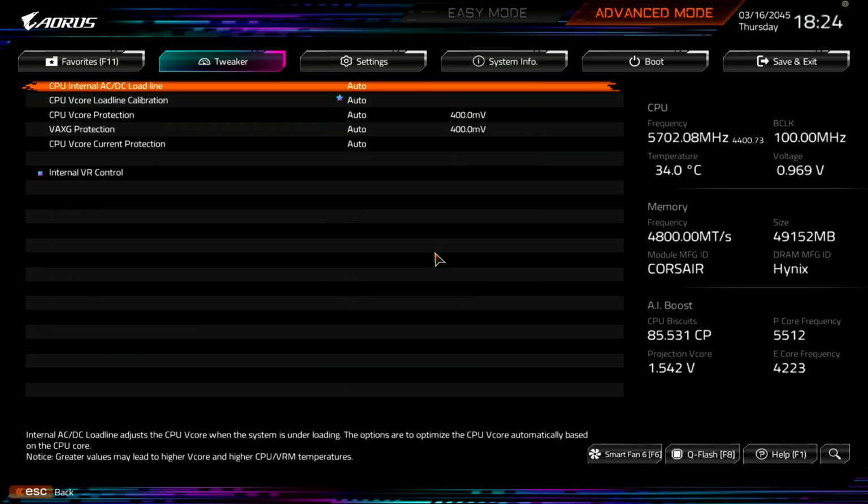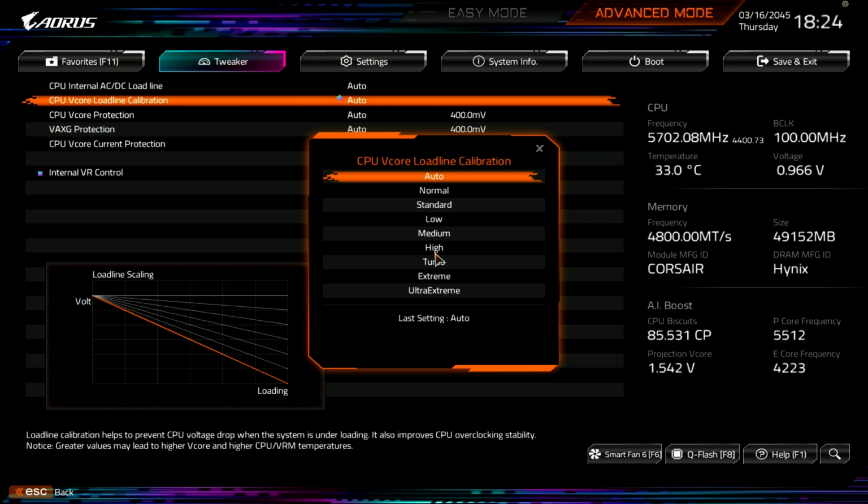And the way I would do this is I would set your load line first and then manually adjust the AC load line down until you start seeing major performance drops. But with Gigabyte motherboards using the Renesas VRM controller, I'm assuming they all have the same load line programmed into the controller. I don't know if that's actually true, but it probably is, because generally Gigabyte doesn't usually give different LLC settings to the same voltage controller across their lineup.